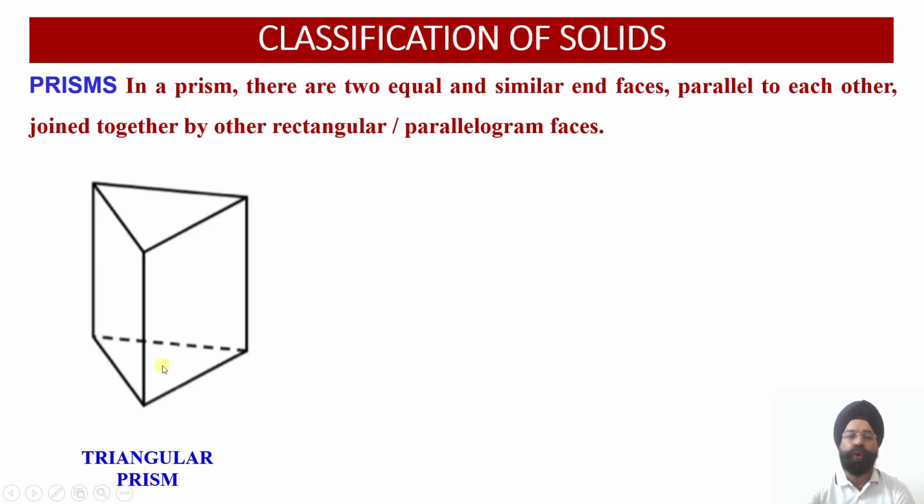Whenever you have the true solid, that is the axis is perpendicular to the base and the solid is standing in upright position, then the two opposite faces of the prism will be joined by rectangles. And if you have an oblique solid, these rectangles will be replaced by parallelograms, right? So now you can see, while we are discussing the basic classification, I am also going to tell you about how we do the naming of each and every point, and how we locate the axis of every solid over here.